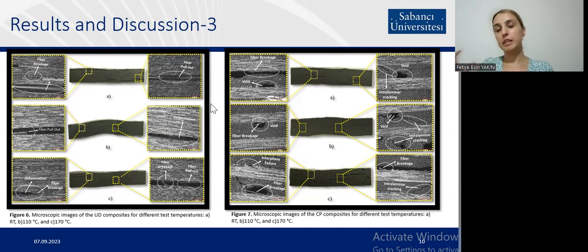Also, we could observe that the bending effect is predominant in the cross-ply laminations, and in cross-ply laminations, voids act as stress concentrations under static loading. Therefore, we can say that even if our void content is less than the unidirectional, we get a different kind of failure type for the cross-ply. Also, a composite is divided into two phases, the fiber phase and the matrix phase.